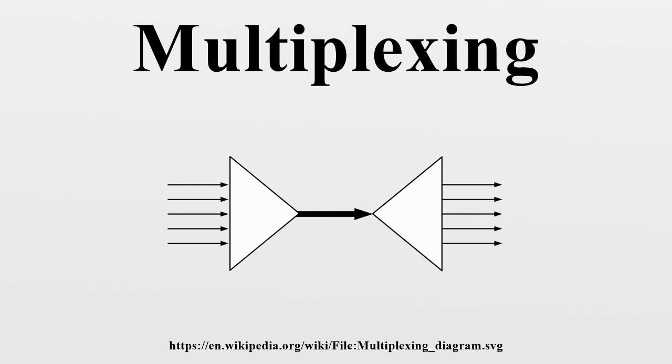Only one cable reaches a customer's residential area, but the service provider can send multiple television channels or signals simultaneously over that cable to all subscribers without interference. Receivers must tune to the appropriate frequency to access the desired signal. A variant technology, called wavelength division multiplexing, is used in optical communications.